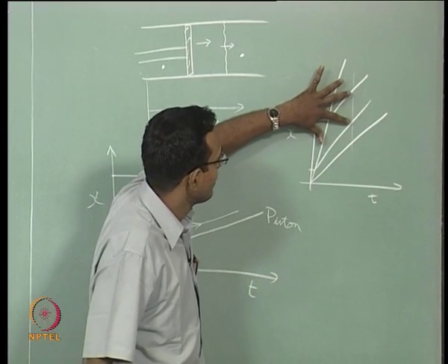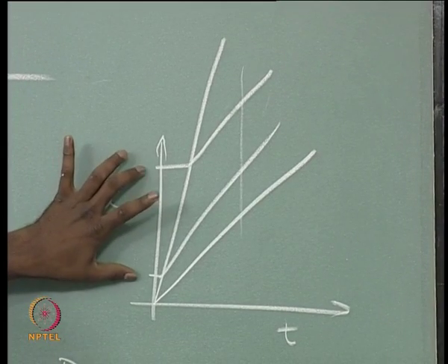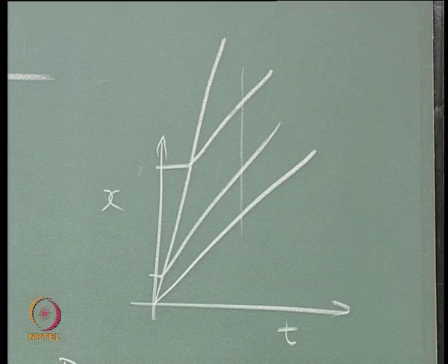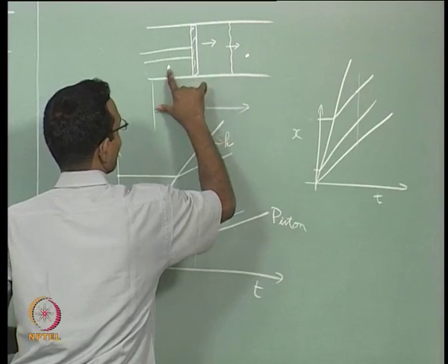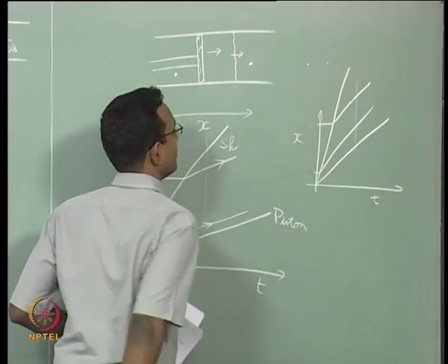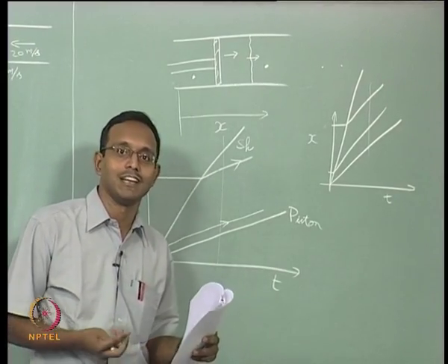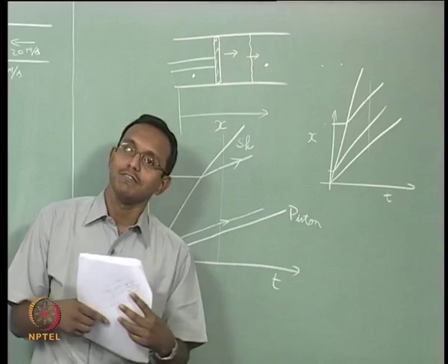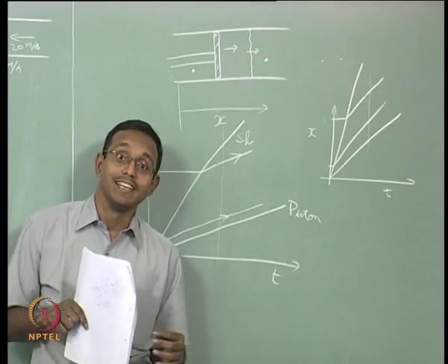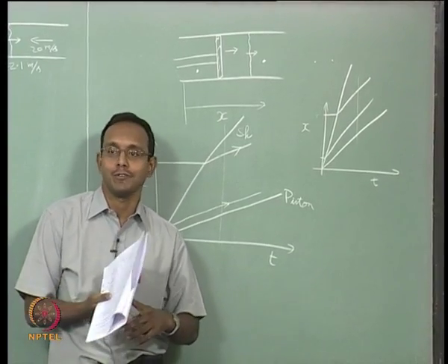Okay. I am going to look at this from here. This much volume is now becoming this small volume. If I had this big separation initially between this and this, the final separation may be just that distance between them. That is also going to happen. This is related to compression. Even when I have the piston moving at subsonic speeds, it is going to cause a shock, which is a compressible flow field phenomenon. Okay.